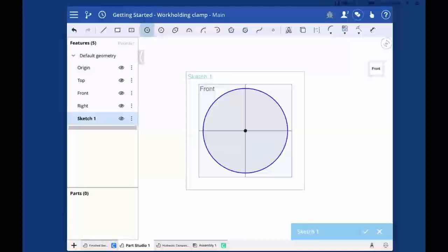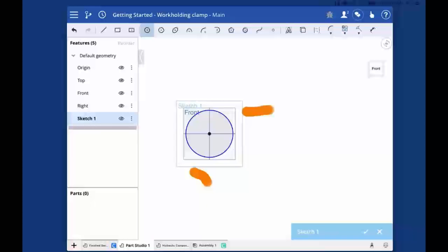And again, the idea there is to mimic what you might do in the browser. I want to be able to mouse over the origin and attach to it. Well, in this case, I hold down my finger and then drag that crosshair over the origin, and then it attaches. Okay, so we'll zoom out just a bit here and do that one more time. I'm still in the circle command. I hold down, call up the precision selector, and move my cursor up. There it is. Let go.